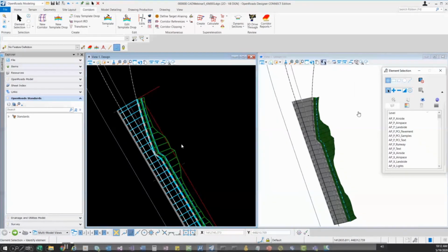Okay, so since this webinar is on corridor edits, I figured I'd go through and show you guys some more edits, just in case maybe you haven't used them yet or don't know exactly how they're working. So I'm back in the same area where I showed the secondary alignment stuff. After I added that secondary alignment and that extra pavement piece for this area, I just added it to the whole corridor, right? So when I did that, it added it here where I don't need it.